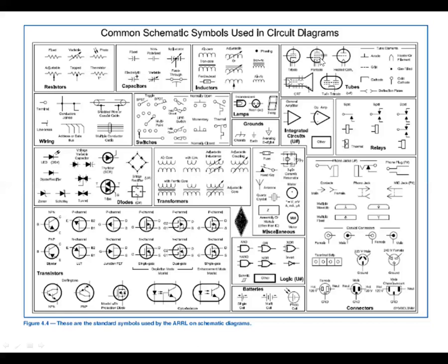And then this would be a pentode because it's got 5 elements: 3 grids, an anode and a cathode. And here's a dual or twin triode, where you've got 2 triodes in the same container, usually a glass container, or I've seen ceramic ones too.